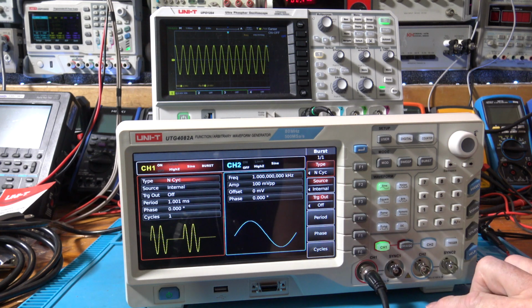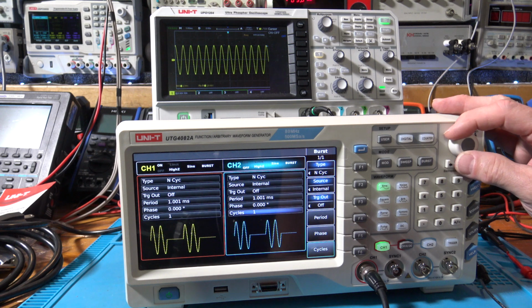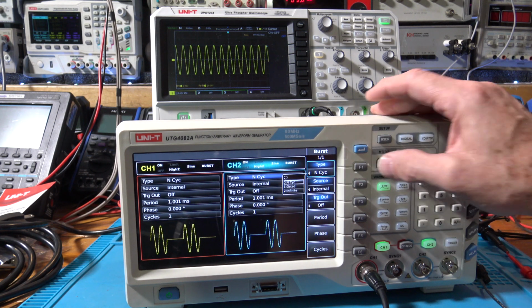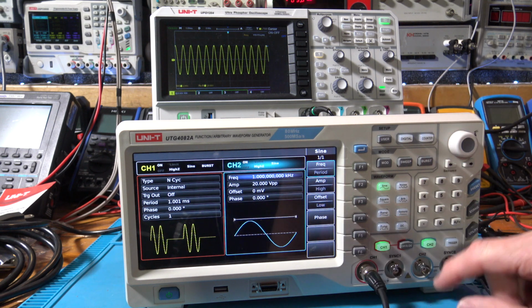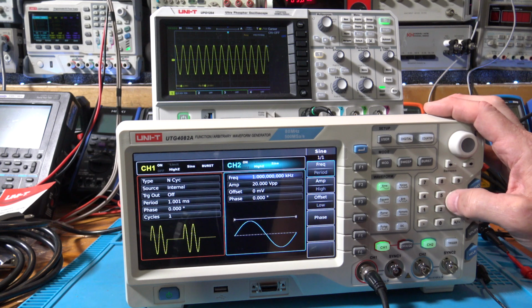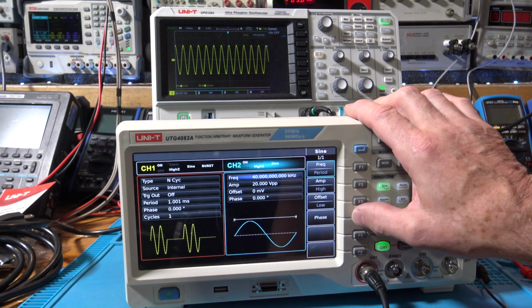Okay, so what else do we have on this one? Here, let's go to channel 2, okay? I want to set this guy up. Okay, I got to get off of burst. Okay, so let's go to channel 2 and set that up for, like, say, 40K. Okay, 40 kilohertz.